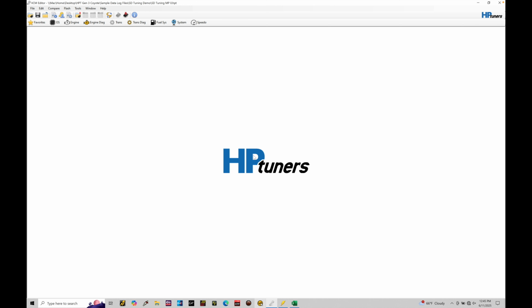Now, in the last training module, we've prepped our VCM scanner in order to go in and data log some specific channels, namely the AC pressure sensor to convert that pressure sensor voltage. There we have our MAP sensor wired in just temporarily, so that we are able to translate that into an actual MAP pressure reading. And then we're going to be doing a ratio calculation between our calculated MAP and our measured MAP so that we can repopulate and renormalize our speed density tables here for a Mustang application.